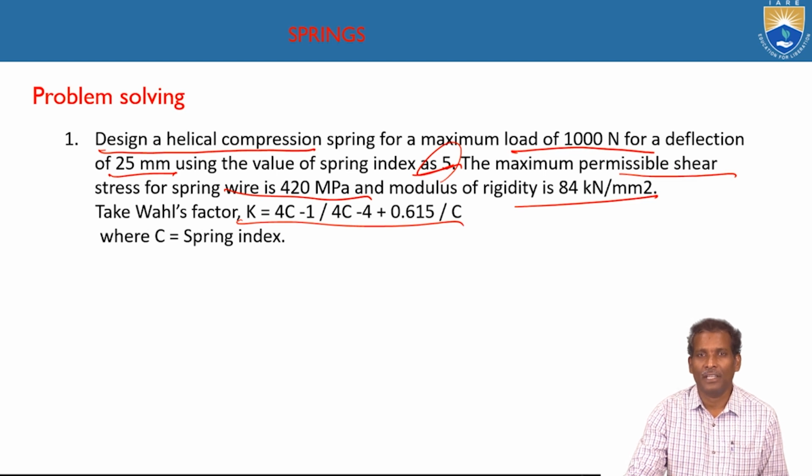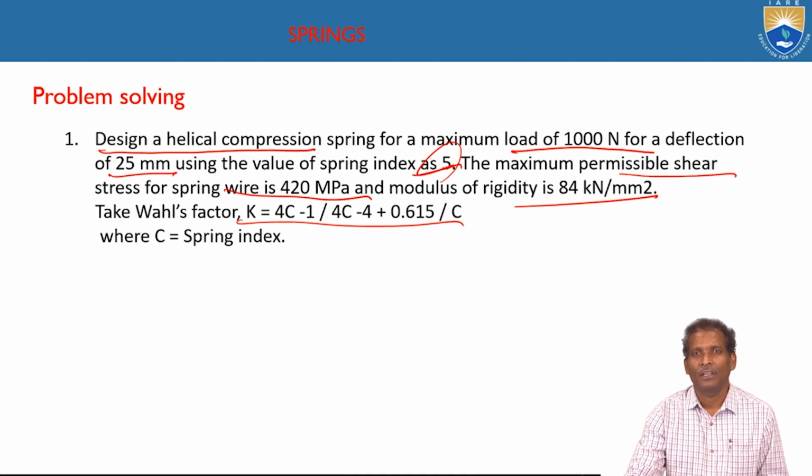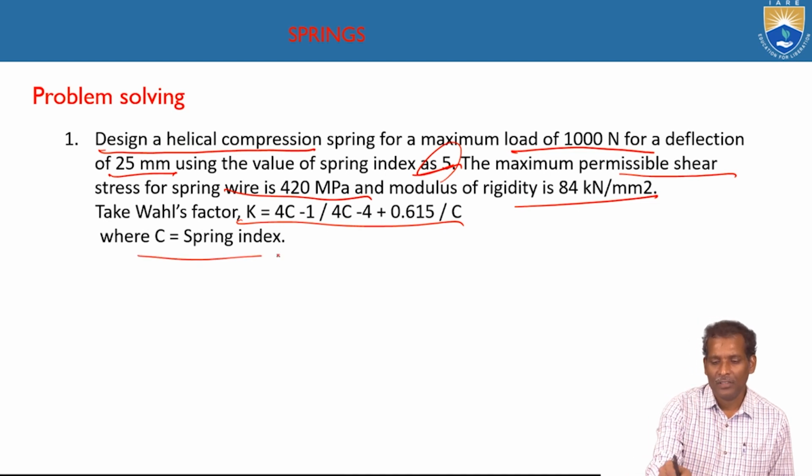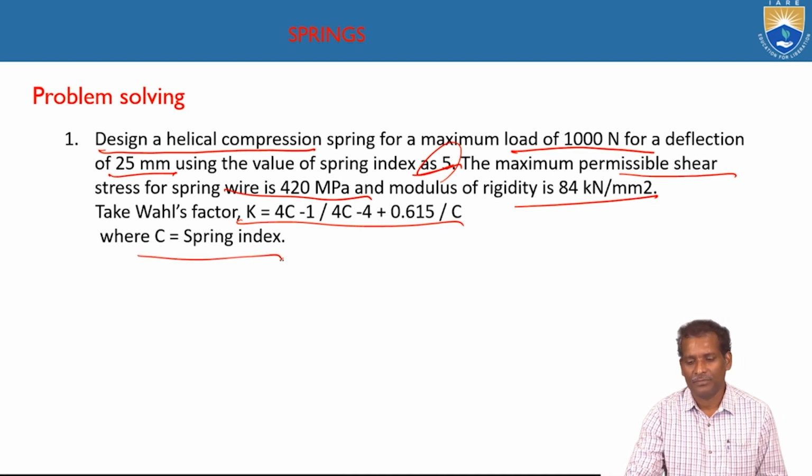So if the wall stress factor is given, it means it is considering the effect of curvature. If not considering the effect of curvature, we have to use the shear stress factor. The spring index is C.